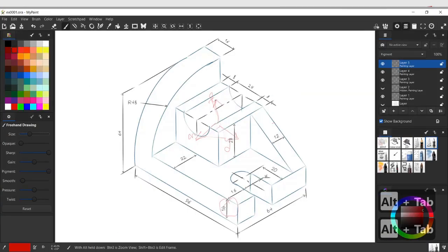So the width of this wall over here is the same as the width of that tab we just created, and then the height of it is 64. One good tip is if you want to use fillet to create this round shape up here, leave the fillets until after you finish the design.